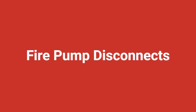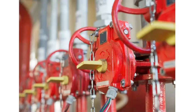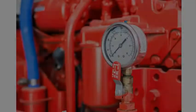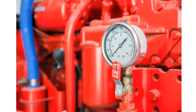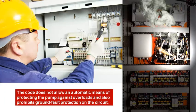Regarding fire pump disconnects, something that may seem counterintuitive at first glance is that the disconnect is locked in the closed position. I can understand making a disconnect lockable in the open position, great idea for maintenance, but lockable in the closed position? The reason is, you don't want that fire pump disconnect left open inadvertently, only to figure out when the building is engulfed in flames that someone accidentally opened the disconnect. The same rationale behind this lock is why the code does not allow an automatic means of protecting the pump against overloads, and also prohibits ground fault protection on the circuit.